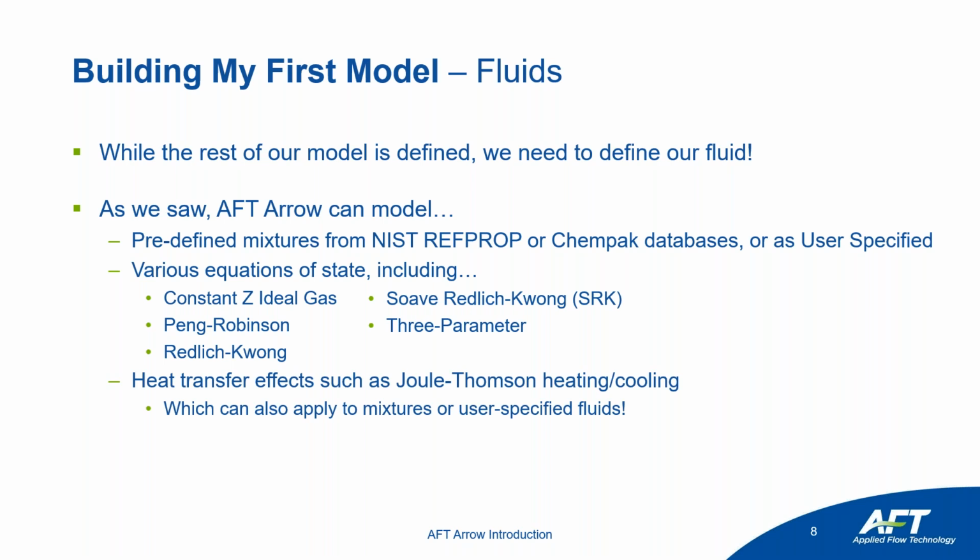As we will see when we run our model, we'll consider heat transfer effects, including the Joule-Thomson heating and cooling effects, whether it's hydrogen and helium, where you see Joule-Thomson heating, or adiabatic cooling for most other gaseous fluids. Again, this will also apply to mixtures. So if you have a natural gas mixture or a mixture of other process fluids or user-specified fluids, we can consider how the fluid properties are going to change with temperature as well.